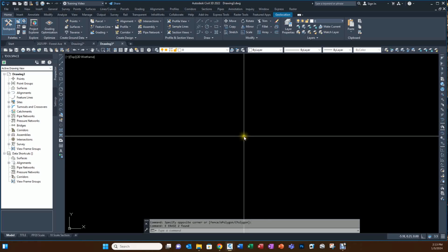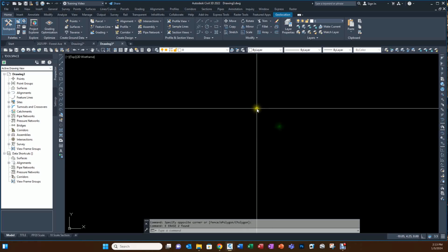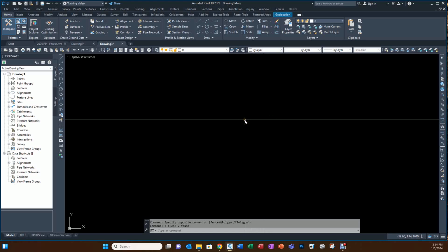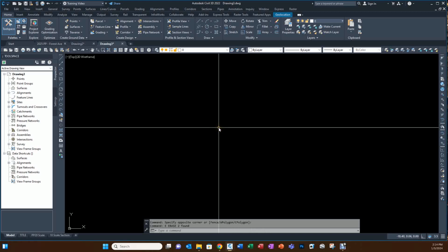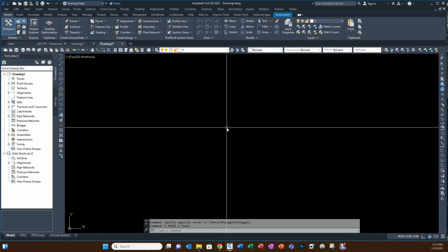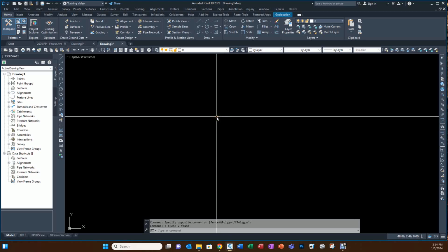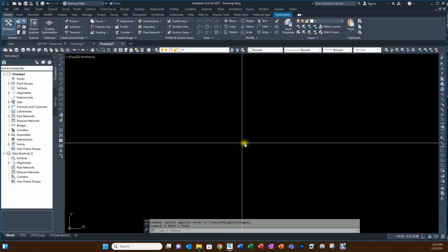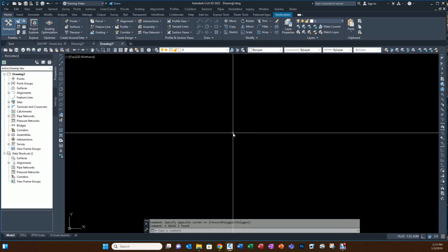You can use the z coordinates also in that. In certain instances, polylines won't accept the z coordinate in different points unless you do a 3D polyline, which is different than a lightweight polyline. But lines will take on all three aspects, the X, the Y, and the Z. So basically, that's kind of the quick version of the how-tos of AutoCAD and its environment.